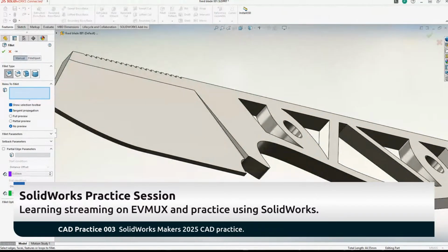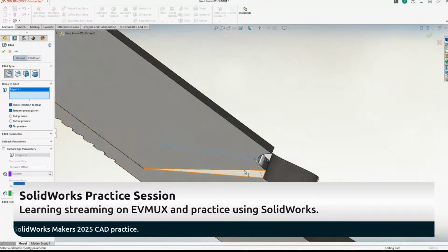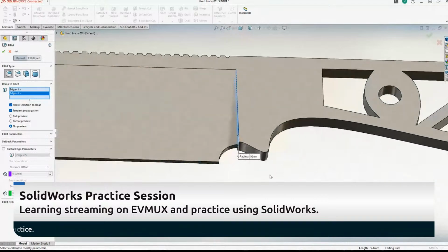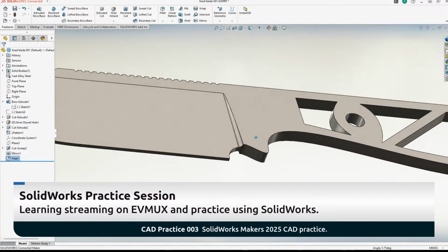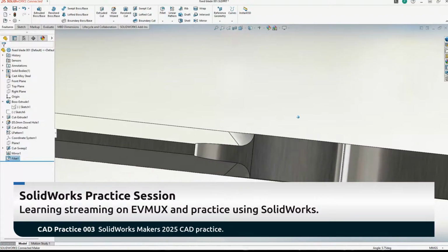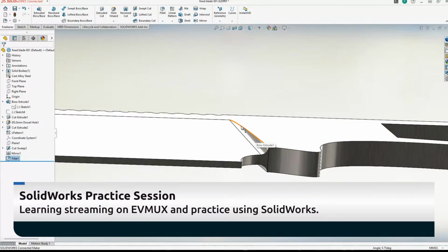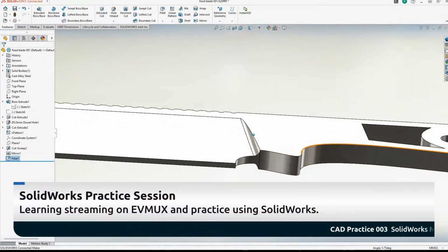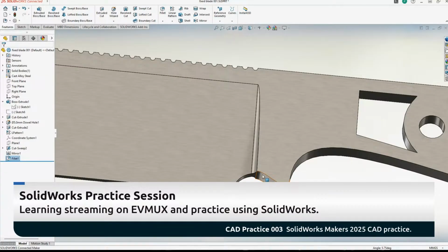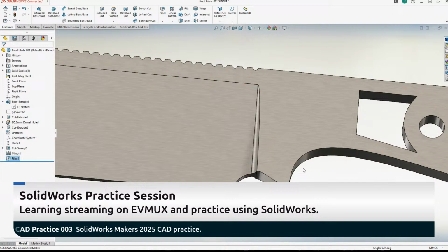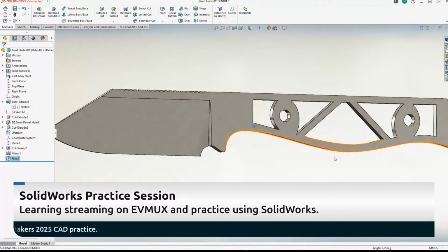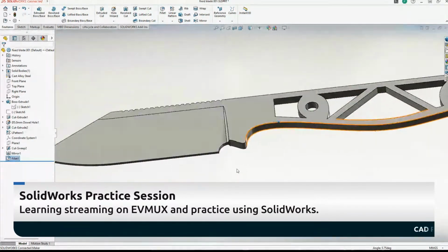Just here. And looks pretty good to me. Once it's all finished, I would go and put a small fillet on every edge, just so even if you don't have a machine fillet, you can tell the machine shop to just hit it with a quick grinder to soften all the edges.